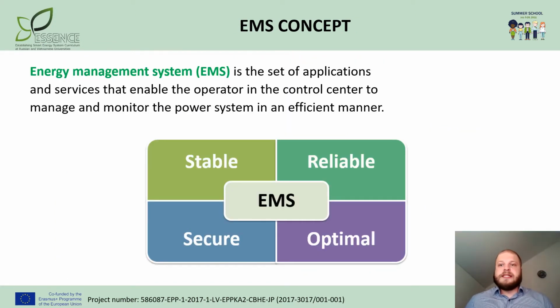An energy management system is usually a collection of computer-aided tools used by operators of electric facilities to monitor, control, and optimize the performance of the generation, transmission, or distribution system. Different computer-aided tools are implemented, from short-time control modules to scheduling or commitment of power production units on a day-week basis. EMS has the objective of maximizing system performance through monitoring and control functions, which require a centralized system of data collection and decision-making procedure.